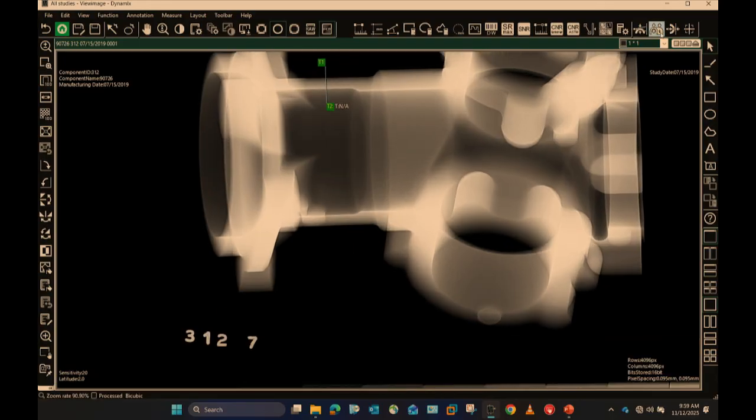So now I can choose this icon and just place it anywhere on the part. And now it's giving me an estimated thickness of that material. So this being darker should be a thinner material over there. So 0.837 inches, 0.433. So a really valuable tool to have. You could try the thicker areas, which are about 1.12 inches. And again, these are estimations, just to see if you're within the ballpark.